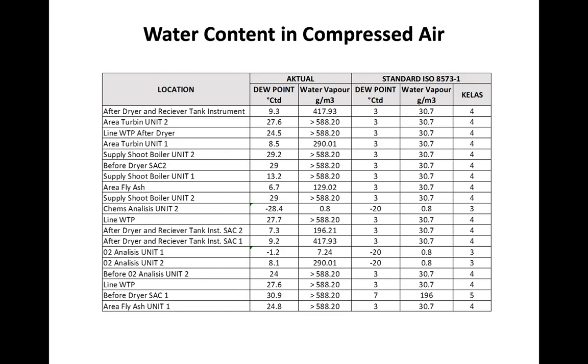For an oil injected screw compressor, they have to lubricate the screw. So this oil will flow with the compressed air through the distribution line. So it will impact the end user of the compressed air, and we will get problems in the future due to the oil content in the compressed air.